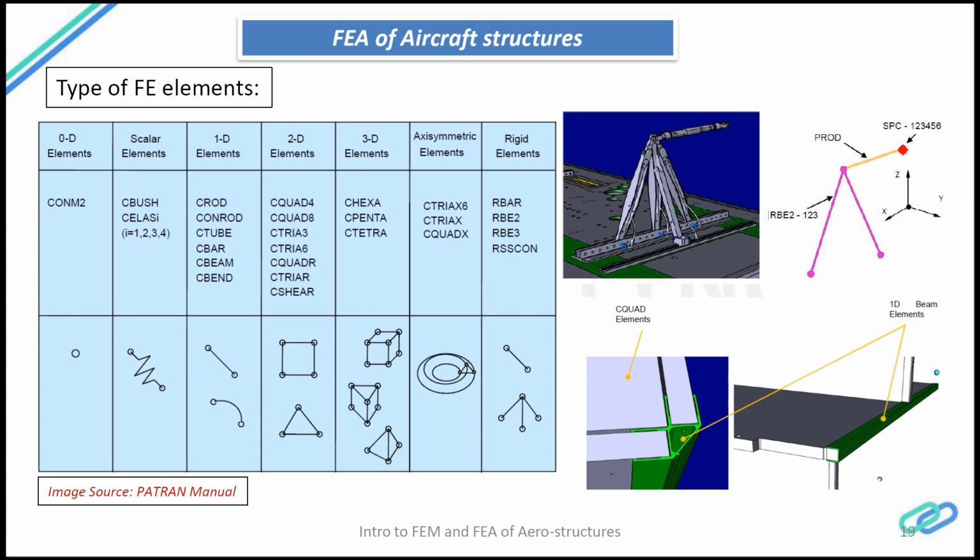Spring element is nothing but your same spring mass system. The spring in the spring mass system represents stiffness. You can specify stiffness along all three directions, or along any one, that is fine. The remaining two directions you can simply put 0, 0. So it can be customized to give stiffness in any of the three directions. Mainly spring elements are used for modeling bolts, fasteners and connections.